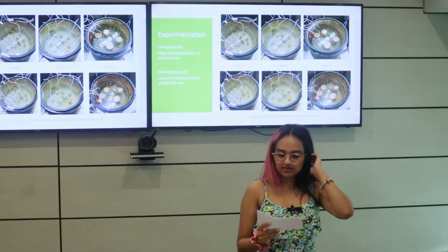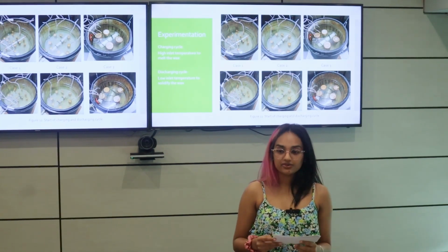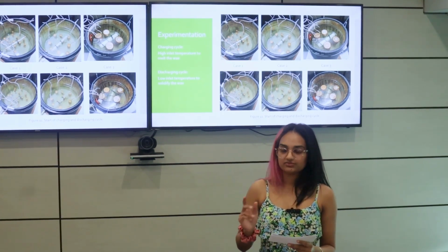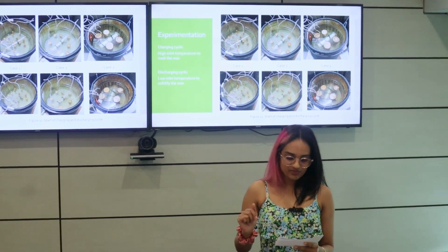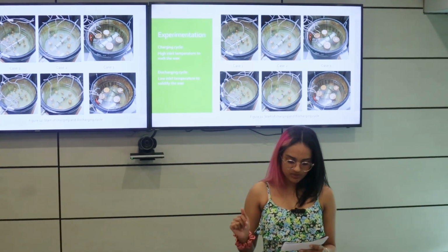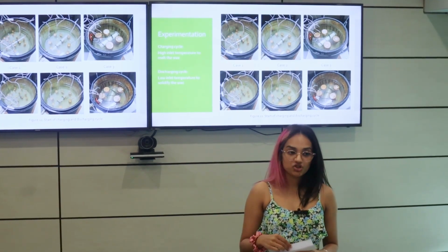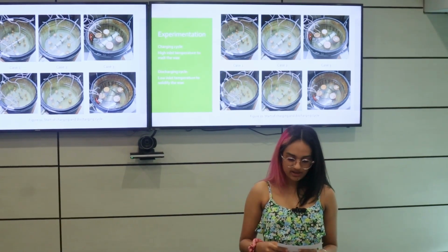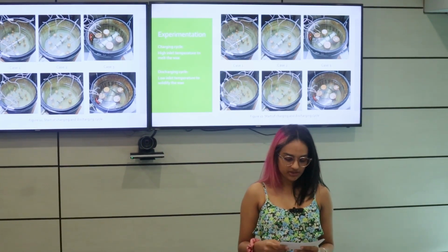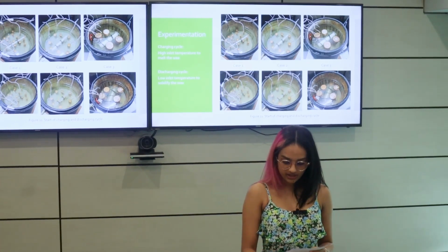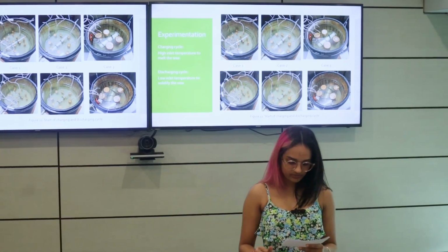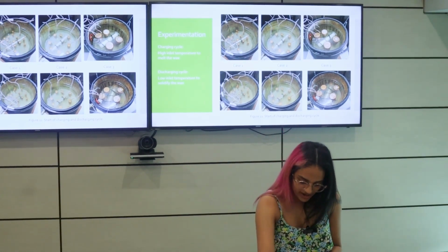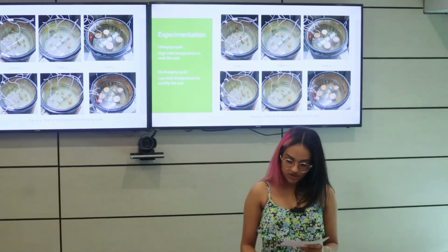In order to quantify the effect of the paraffin wax, I did the experiment in 2 phases, 2 phases for each case. First, it was the charging cycle, which is then immediately followed by the discharging cycle. The charging cycle begins with the tank filled with water at 20 degrees Celsius, as can be seen in figure 11, the top row. The wax can be seen to be completely white and solid at the beginning of the charging cycle, which is what you're seeing inside those acrylic tubes.